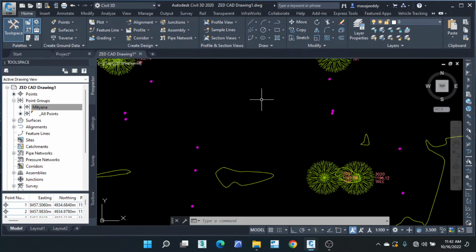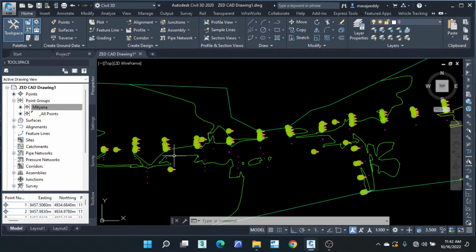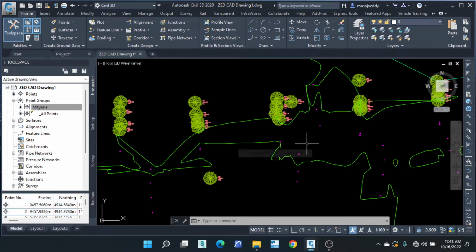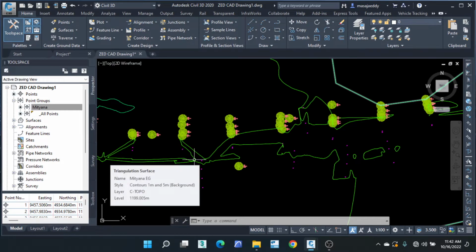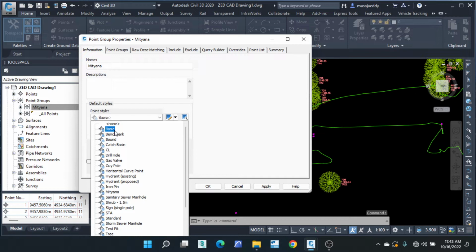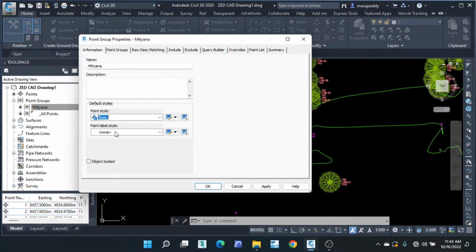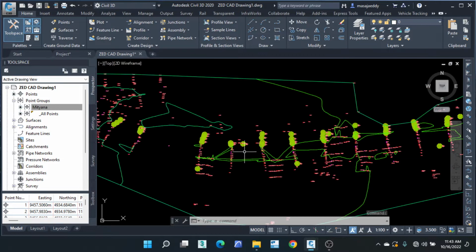Of course, there are multiple center lines that were created, but remember, we are following a certain center line for us to upgrade this road, right? So the center lines are the ones that are going to be our marking points for whatever we're going to be designing our alignment with. So I'm going to right click. Let me first go back to where we were. It was basic. Then this was, let me use description only. So we had something that was crowded that way, right?